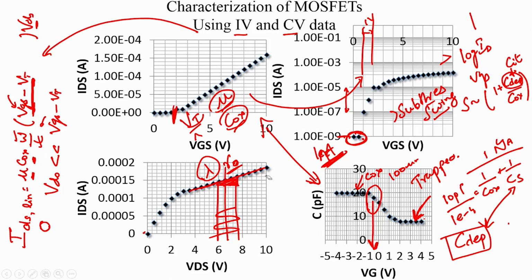Which is to say that if you have an ideal MOSFET with no channel length modulation, in saturation operation there is supposed to be no current variation in this MOSFET, but we then use this ideal MOSFET and add a resistor in parallel, so that when the MOSFET operates in saturation the small signal current here is 0, whereas the small signal current in the resistor is not 0, and it is in fact defined by the current variation in saturation mode.